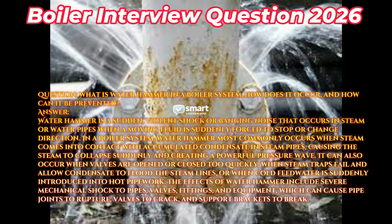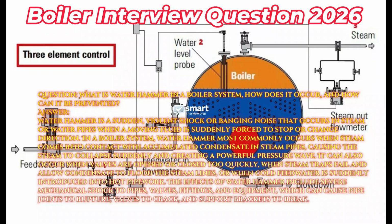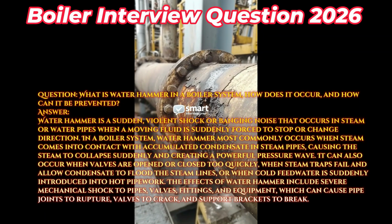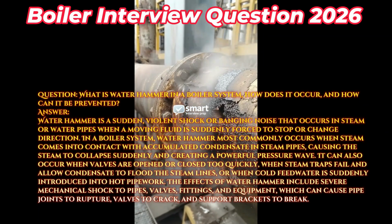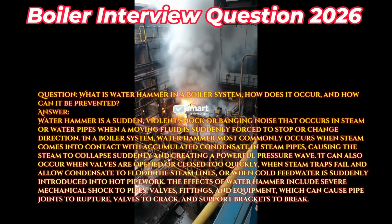Answer: water hammer is a sudden, violent shock or banging noise that occurs in steam or water pipes when a moving fluid is suddenly forced to stop or change direction. In a boiler system, water hammer most commonly occurs when steam comes into contact with accumulated condensate in steam pipes, causing the steam to collapse suddenly and creating a powerful pressure wave.